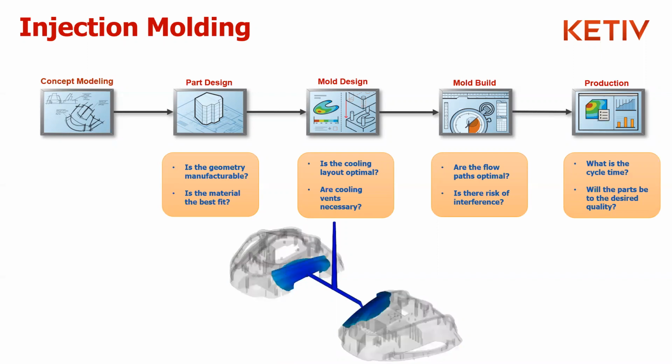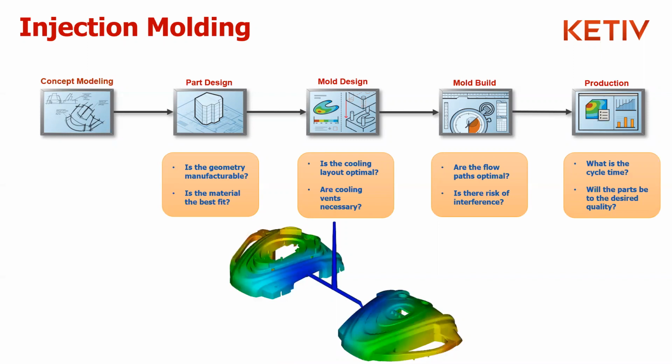Now, again, this is a number. Sorry, I was just going to add a comment that, every time I look at this, the real striking point is the evolution of details and also variation. Of course, when you start with a single part or design concept, everything's less complicated, and you can make some really great choices with those assumptions. But you don't want to negate the amount of detail that's going to come downstream, because you can still get fooled. A single part only feels great, but what happens when you add details like runners, gates, cooling? It's an evolution of variation too. If you can get it more uniform at the part level, you have less variation when you get to these other complex details. So it's an interesting trend of details and variation, and variation is the devil when it comes to plastics.